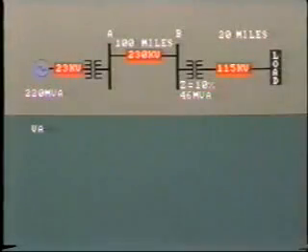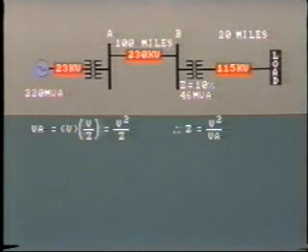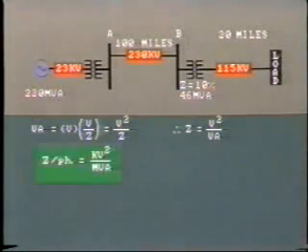But shouldn't the impedance be indicated in ohms? Well, the answer is yes and no. Not necessarily, and I'll show you what I mean. If we do need to calculate ohmic impedance, we must remember the relationships between VA, voltage, current, and impedance. First, VA, voltage times current, equals voltage times voltage over impedance Z, or V squared over Z. By transposing, we find that Z, impedance, equals V squared divided by voltamps. In terms of the power system, impedance per phase equals kV squared divided by MVA.